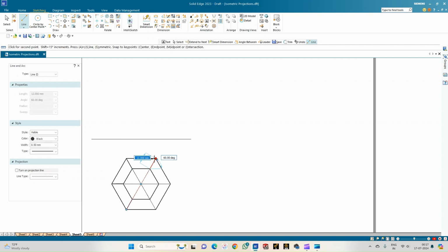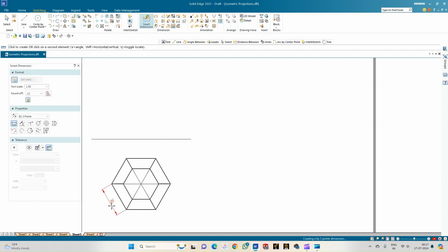So this completes the first solid, that is the frustum of the hexagonal pyramid, whose bottom face is measuring 30 mm and the top face is measuring 18 mm. So this is the parameter that is given to us. Also, he tells that the axis of this frustum of the hexagonal pyramid and the sphere is coinciding.